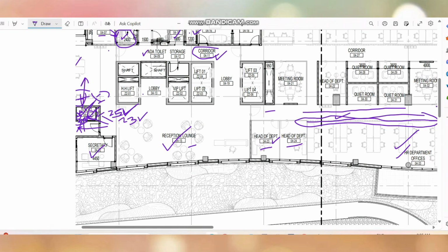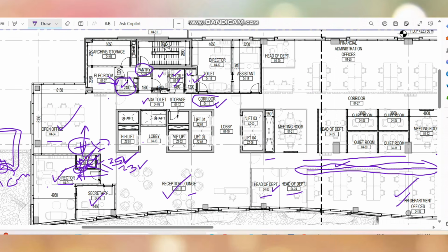So conceptually, let's say you have three toilets here, and inside the toilets we have negative ventilation. To compensate the exhaust, for the three toilets 75 liters per second is the exhaust. So we have to provide the fresh air. It will take the additional fresh air through the door undercut from the nearby area. From this nearby corridor area it will take the fresh air, so it will be properly circulated and compensated. So we can provide this additional fresh air of 65 liters per second to the corridor area, the reception area and different corridor areas. So the overall floor will be positive ventilation.